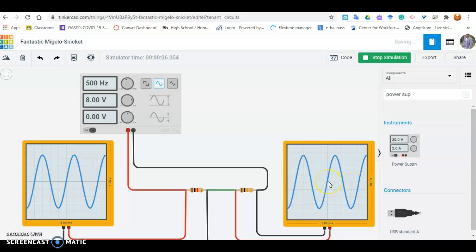That makes sense. You take 1 divided by your frequency to get your period of your waveform. 1 over 500. That is 2 milliseconds. And so you see that here's 1 millisecond, and then 2 more squares. That's 2 milliseconds. So we're able to gauge that also in this lab in terms of the frequency of the waveform.